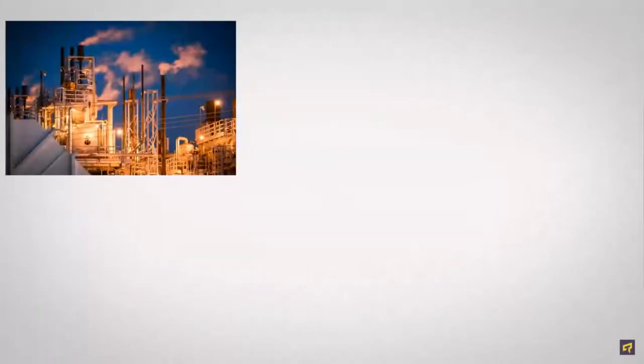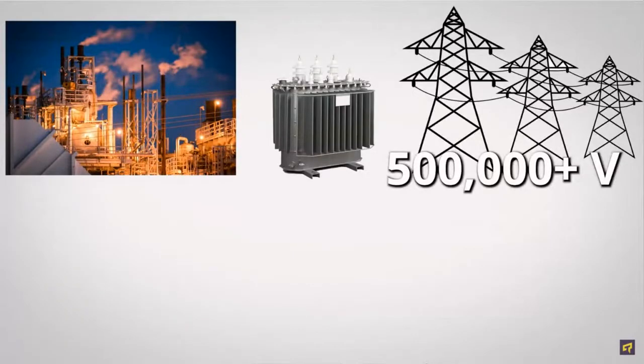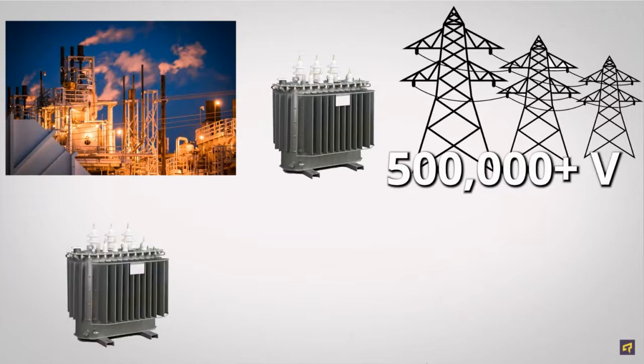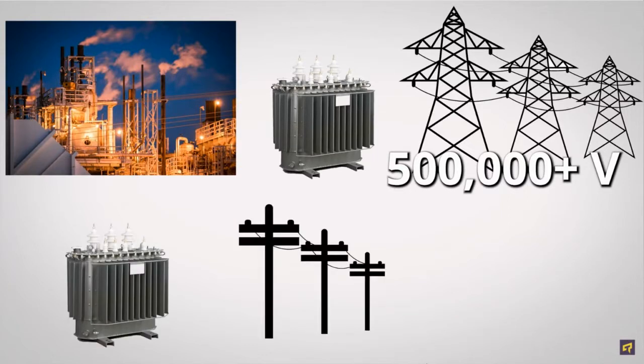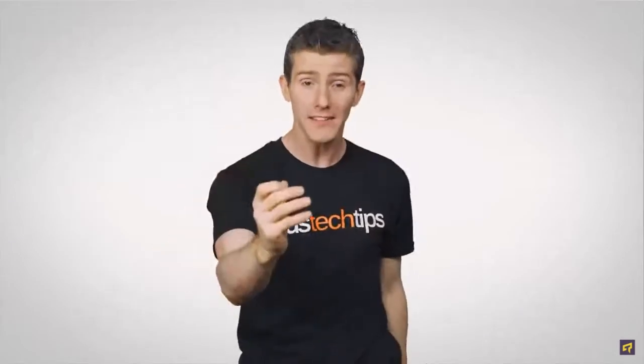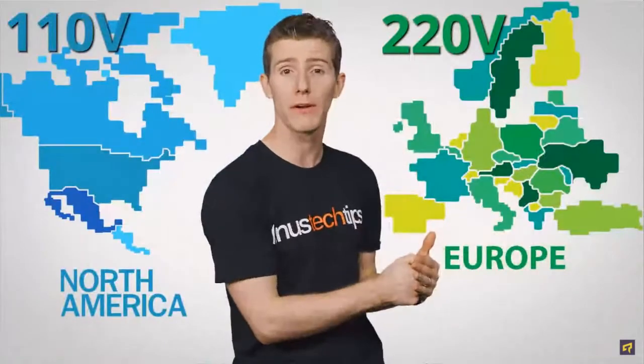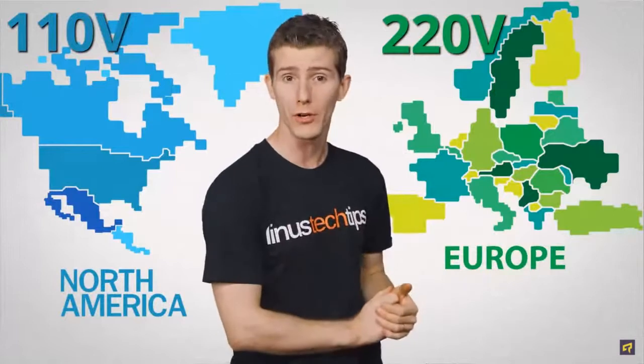You see, when an electrical plant spits out power, the voltage is stepped up to hundreds of thousands of volts. This is because high voltage electricity is more efficient to send over long distances. It helps prevent power loss. But before it reaches your home, a series of transformers is needed to lower that voltage down to a safe level so that you won't get fried every time you try to plug something in. So that's 110 volts if you're in North America, or 220 if you're over in Europe.